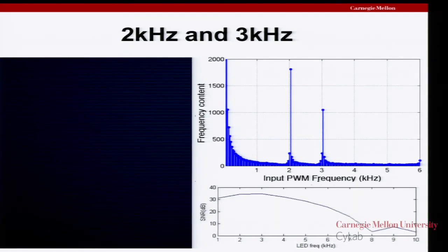And so if you plot the signal to noise ratio across the different LED frequencies, you see a curve that looks kind of like this. We know one side of this is limited by what people will detect as flicker, and then we start to see some attenuation pretty harshly above around 7 kilohertz. This data was taken on iOS type devices, which we think are pretty representative. So that means we have a bunch of bandwidth there, which we can now modulate frequencies over.